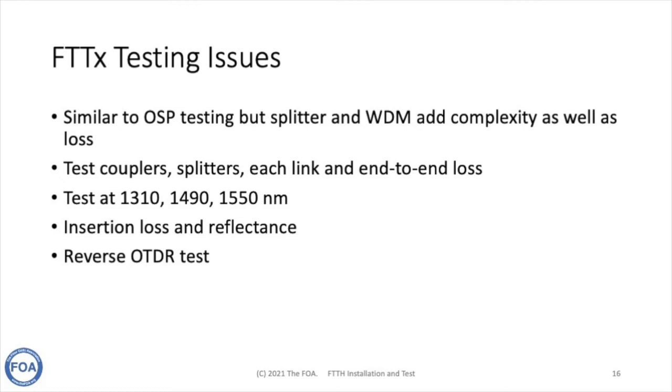OTDR testing, if it's done, requires special OTDRs generally because the lengths are short, and OTDRs are really primarily designed for long-haul networks. There's also some quirks in what happens when you use an OTDR on a network with a splitter, and we'll look at that in a minute.